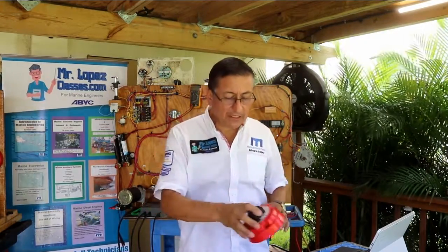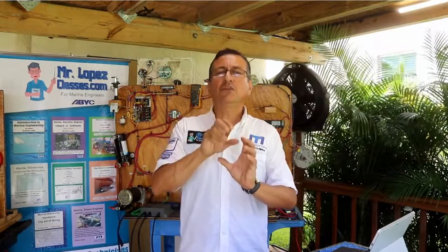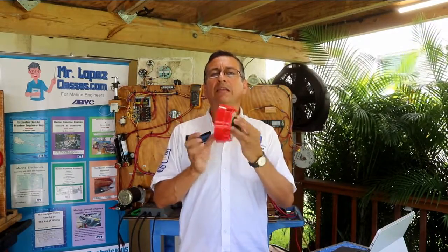How can I select my battery switch selector? I select it according to the capacity of the battery banks in amps per hour. How do I know what is the maximum capacity of my battery switch selector? You add the capacity in amps per hour of both battery banks, and you add 10% additionally, and this is the capacity in continuous operation that the switch selector should support. Simple. The capacity of the battery switch selector depends on the capacity of the battery banks.